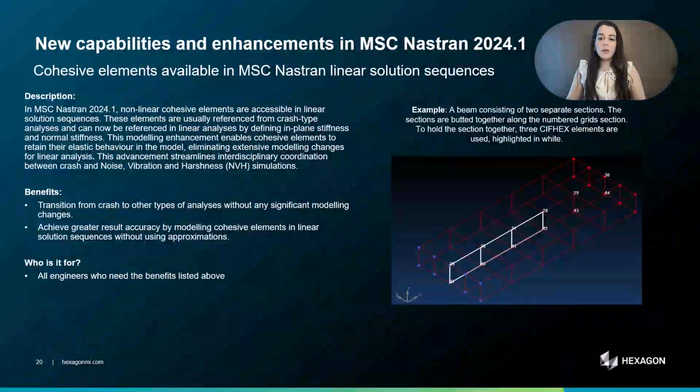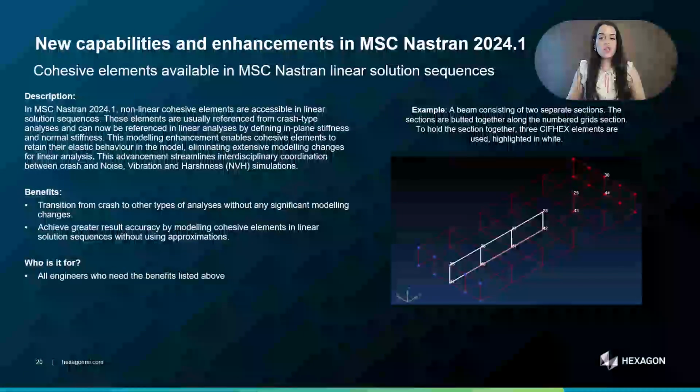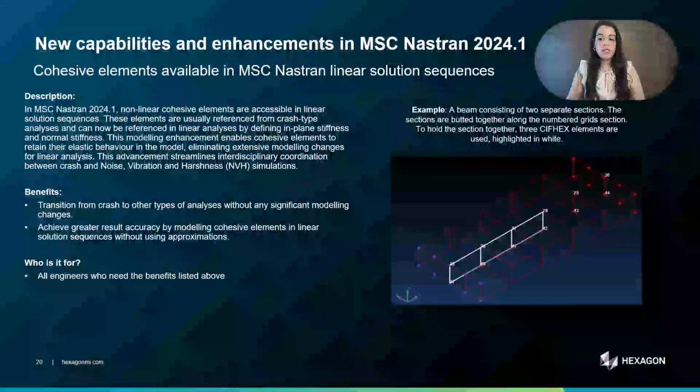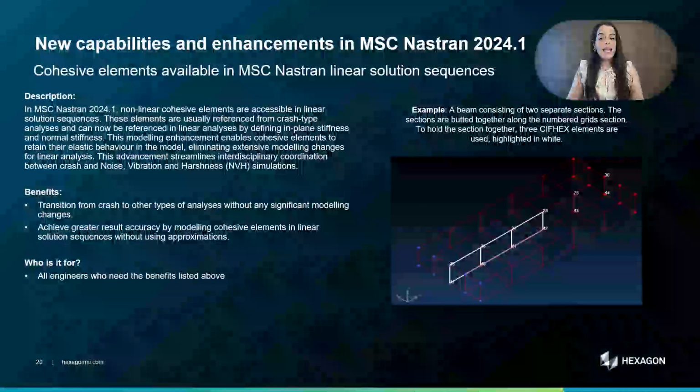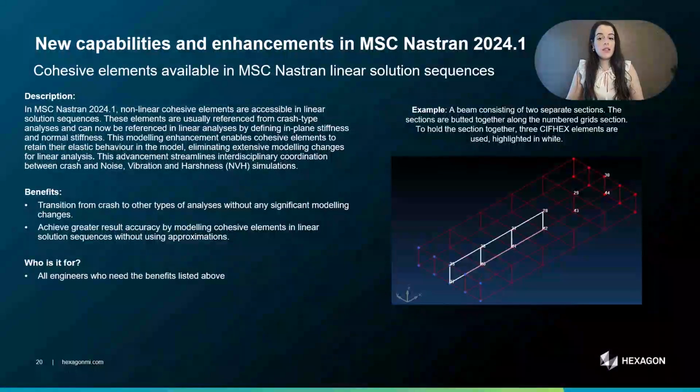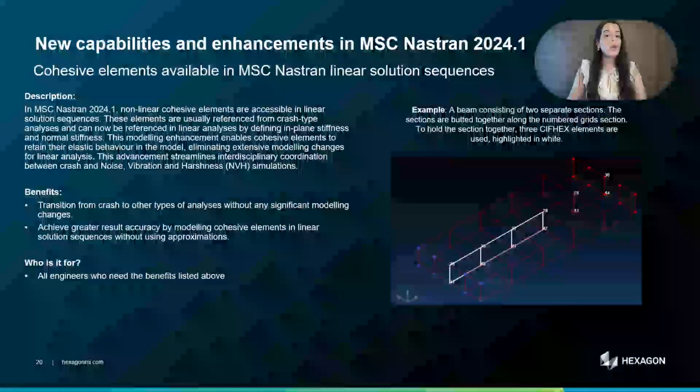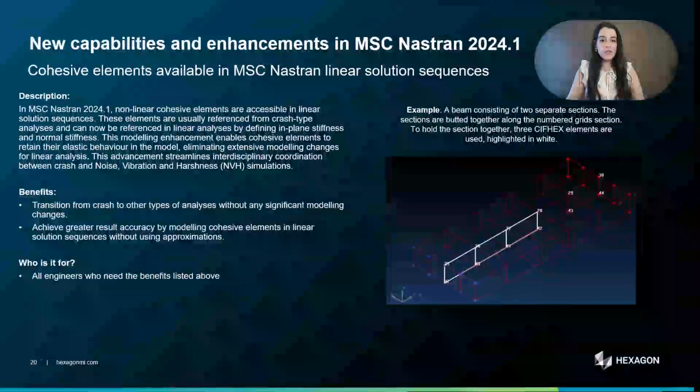The benefits include the ability to transition from contact to other types of analysis without significant modeling changes and achieve greater results accuracy by modeling cohesive elements in linear solution sequences without any modeling approximations.